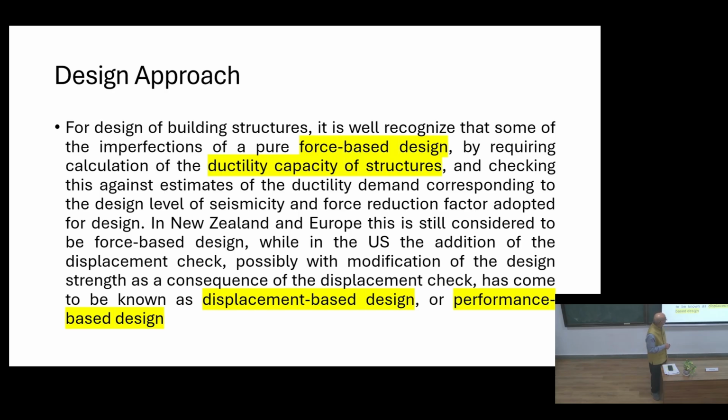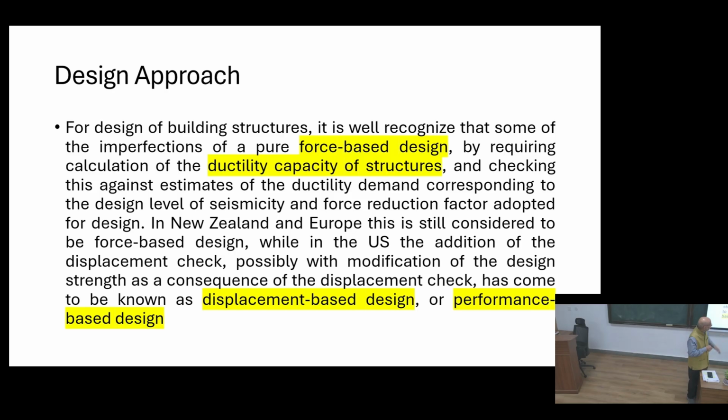Then, as we have seen with the performance point, how much deformation is taking place in the structure. When you apply the force, deformation takes place. How much deformation is there? How much capacity is there? The capacity of the structure depends upon how much ductility there is, which comes through the stiffness of the structure, so it will deform accordingly. So you fix the performance point according to the capacity of the structure, and you design it.